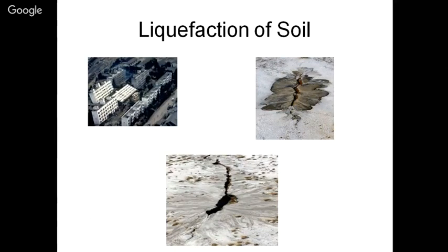Liquefaction of soil: as we all know, shear strength of the soil is the major concern and criterion to evaluate soil conditions. For an earthquake, as the motion is vibratory, to and fro motion, the soil loses its shear strength because of this to and fro motion. Shear strength can be evaluated at lab level or in situ level by various ways.